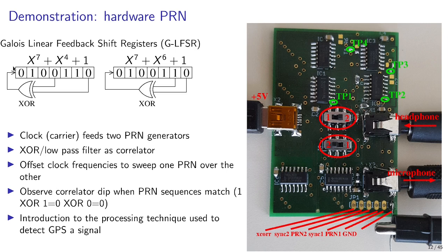Actually, one quantity is forbidden because we see here that we are going to feed back as the input of the linear feedback shift register the XORed values of two positions within the register to try to create this 2 to the n length sequence. And if we had all zeros, 0 XOR 0 will output 0 and the register would remain in the 0 state. So actually 0 is a forbidden state, and we end up having a length 2 to the n minus 1 sequence, a non-repeating sequence, encoded by a register of n bits long.